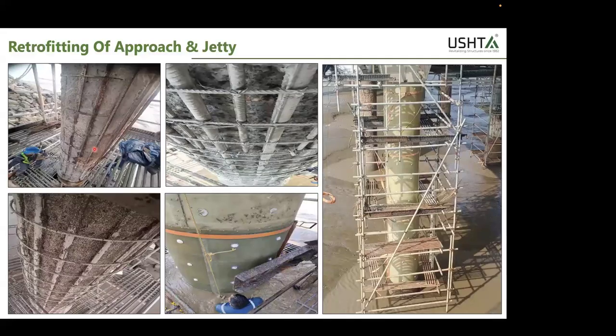Now, the second line of defense is that we apply a water curable epoxy layer, which will cure underwater also, and sprinkle sand on that. How it works is it will chemically isolate the old and the new concrete and physically bond them. I repeat, it will chemically isolate the old and new concrete and physically bond.